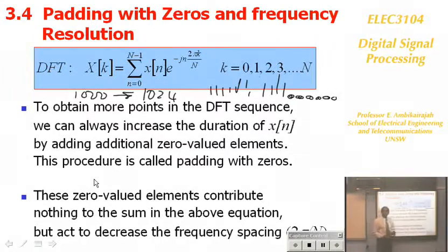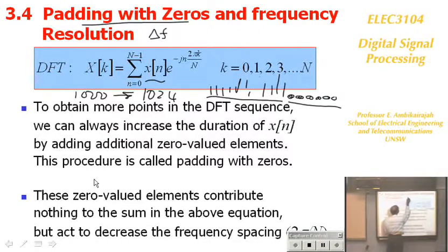By adding zeros, you are not changing the amplitude of the waveform. If you think about it carefully, no, you're not. That's called padding with zeros. By adding zeros, you are making your number of samples 1024. That allows you to apply the fast Fourier transform. And not only that, these samples are that, and by adding extra zeros, you are not going to change the summation. But what you are doing is, your frequency resolution is sampling frequency over number of samples.